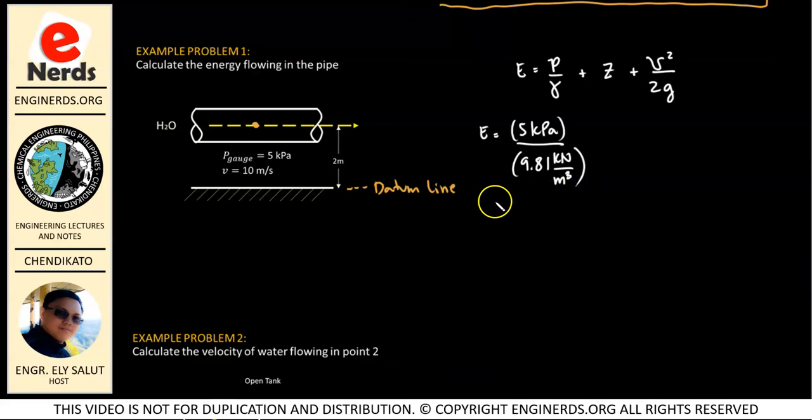Now, how did we get that? The unit weight is equal to the density of the material times the acceleration due to gravity. Okay? So for water, the unit weight of water is equal to the density of water, which is 1,000 kilogram per cubic meter, times the acceleration due to gravity, which is 9.81 meters per second squared.